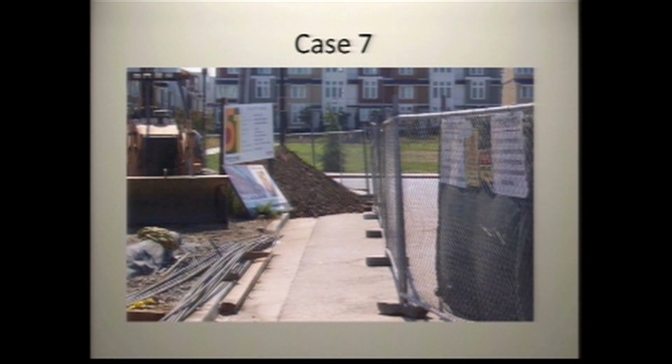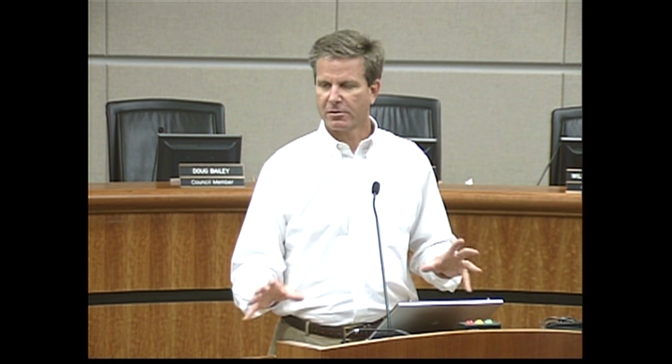You can see some other materials, some rebar lying there. That's not good housekeeping. It's not a real environmental concern. You know, construction materials in their final form aren't a problem. When they're stockpiled, they can be. You're going to get elevated iron levels coming off of that pile of rebar. Is that an environmental problem? No. I mean, iron is not that toxic, and it takes a lot of it to cause toxicity. That, strictly speaking, should be back and under a cover.